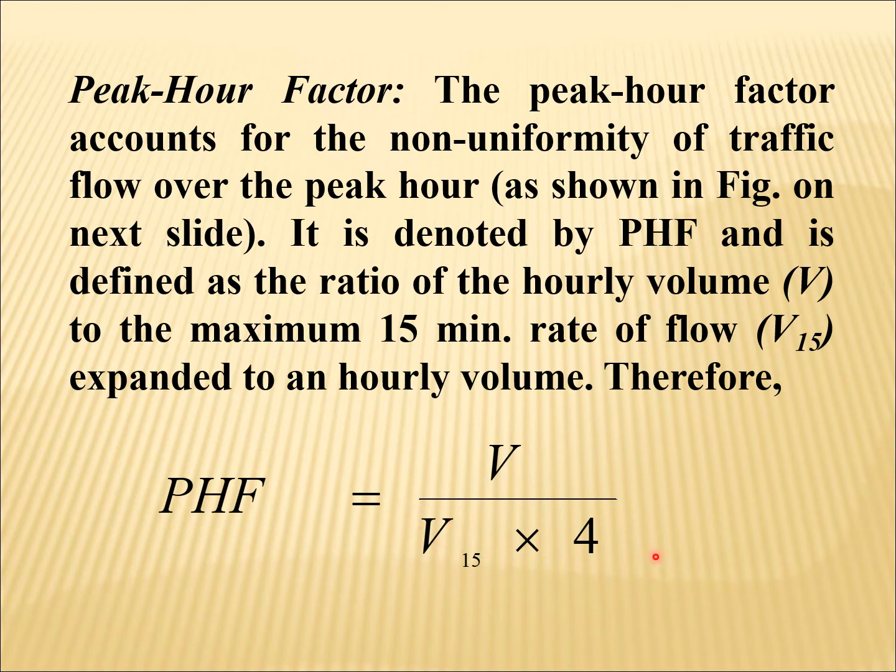So again look at the definition. PHF, that is the peak hour factor, is defined as the ratio of the hourly volume V to the maximum 15-minute rate of flow expanded to an hourly volume. So look at this formula. This is the formula for PHF.